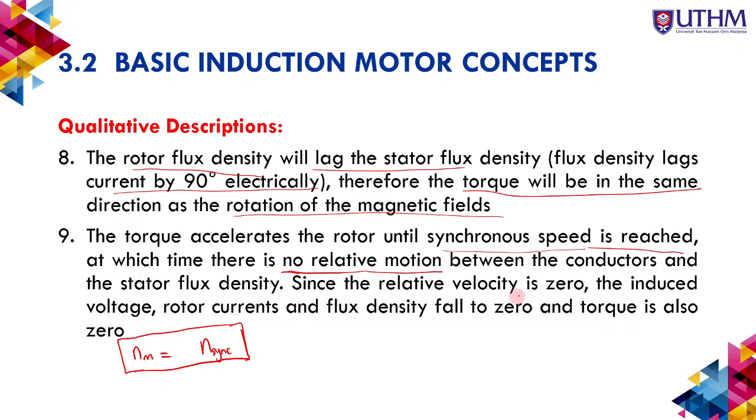Since the relative velocity is 0, the induced voltage is 0. Induced voltage, rotor current, flux density all go to 0, and torque is also 0.